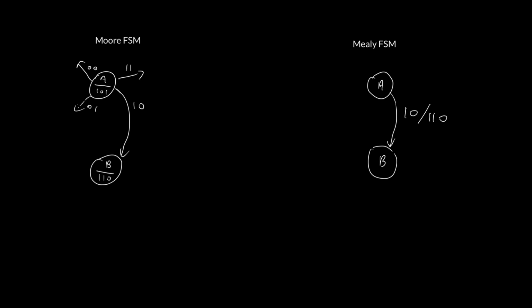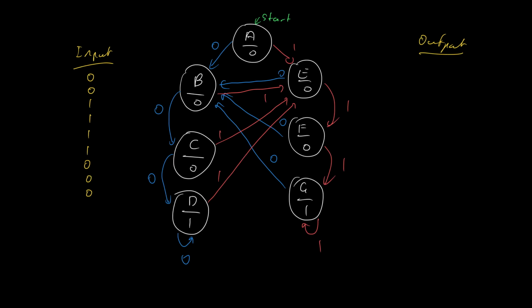We're going to focus mainly in this course on Moore finite state machines. It is possible to convert between the two. There is perhaps a slight delay. You might lose a clock cycle. A Mealy finite state machine is very general. A Moore is a restricted finite state machine. But usually the benefits outweigh the restrictions. So we normally use a Moore finite state machine.